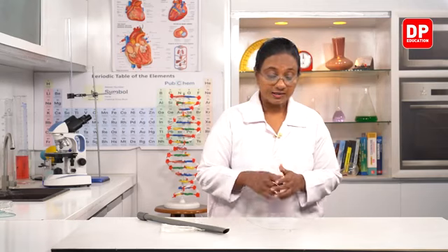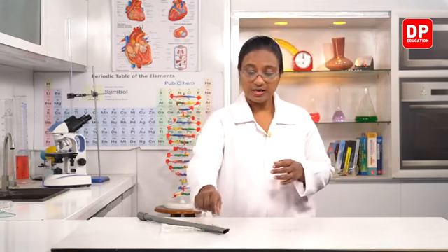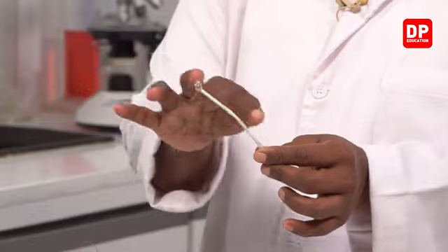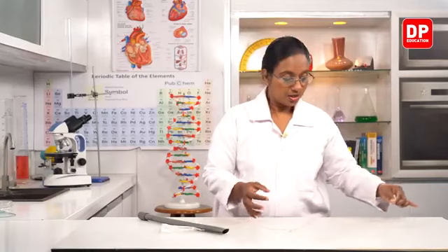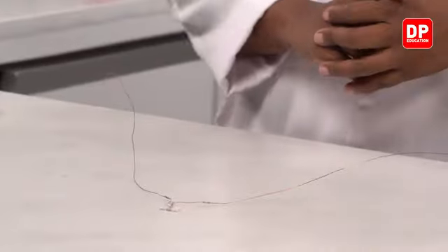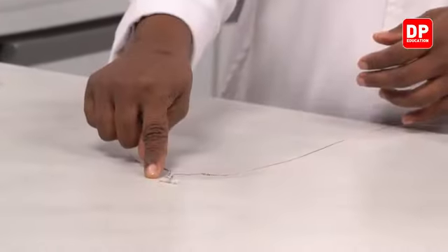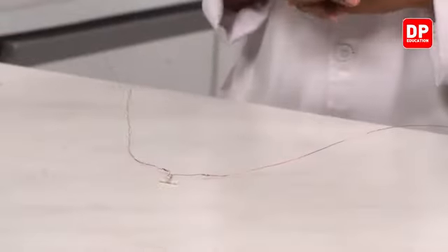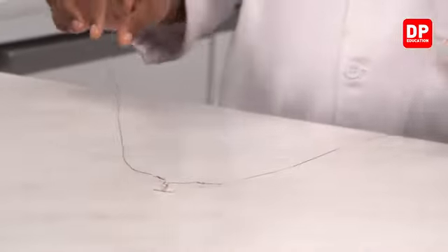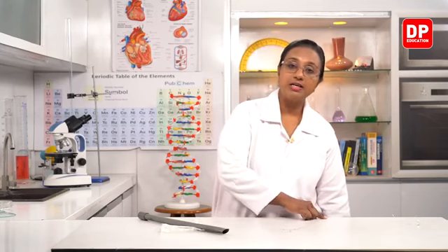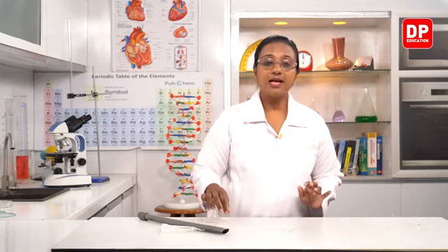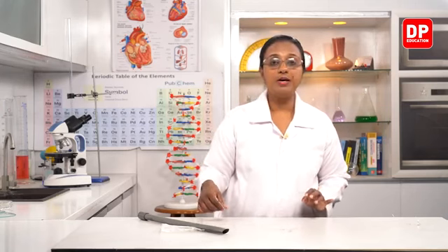So to do that activity, we need a neon bulb. So here I have a neon bulb and the two terminals of the neon bulb are connected to conducting wires, copper wires. So similar to that, here I have another neon bulb. I have attached it to the surface so that it won't move while I do the activity. And here I have connected the two terminals to copper wires. And on this side, I have a long wire that is connected to the earth there. So it's a long wire. Whereas on this side, I have the terminal with the open end.